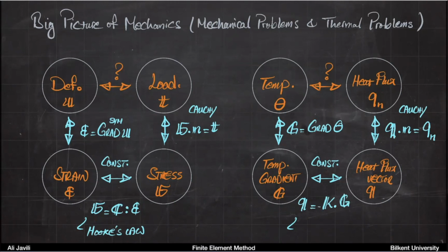Just historically, there is a minus here because usually if something cools down, the heat flux is negative or something. So that is usually a definition that you have in fluid mechanics or in thermomechanics. So I keep that factor minus for notational convenience, but it could be also inside K. Now, K is exactly the conductivity.